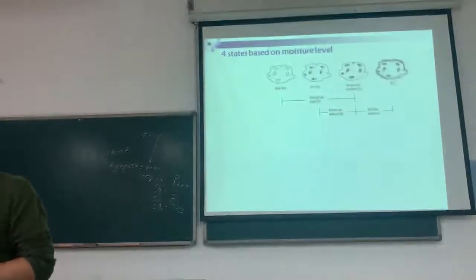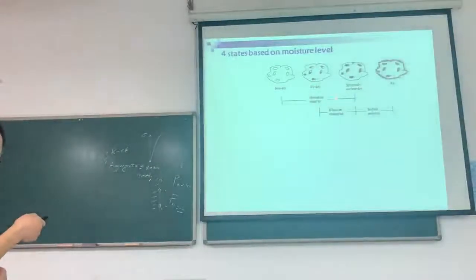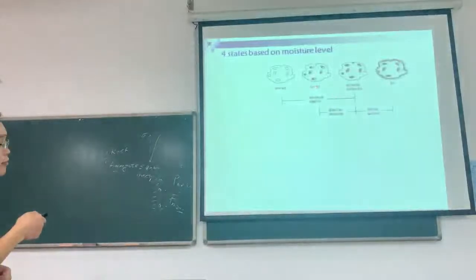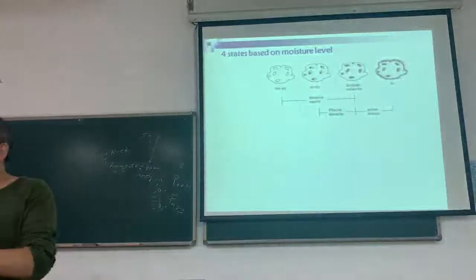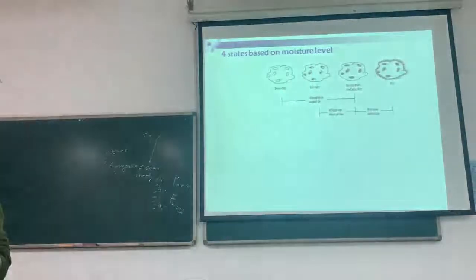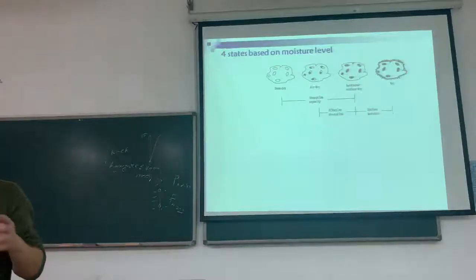And in the construction fields, the aggregates may be at this air dry state. Yeah. But for the asphalt concrete, they also need to be oven dry. When we mix the asphalt concrete, the first thing we need is to heat the asphalt and heat the aggregate.